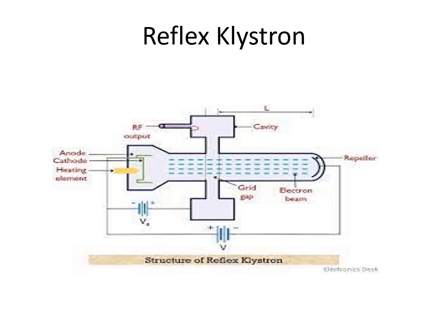Hence early electron and late electron appear at the gap at the same instant. The late electrons that pass the gap later than the reference electron experience a maximum negative voltage and move with retarding velocity. The return time of these electrons is less and they catch up with early electron and reference electron and form a bunch.